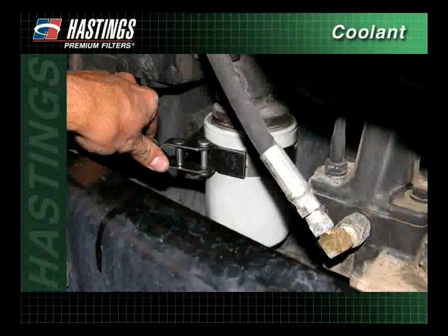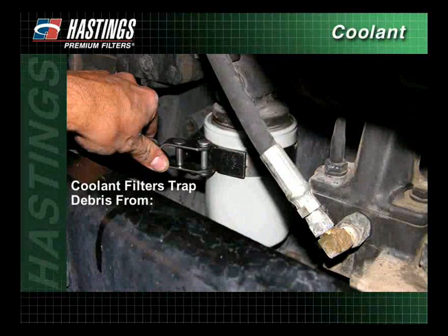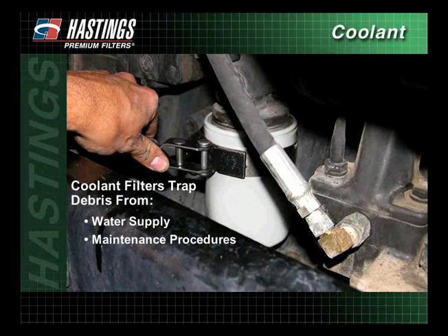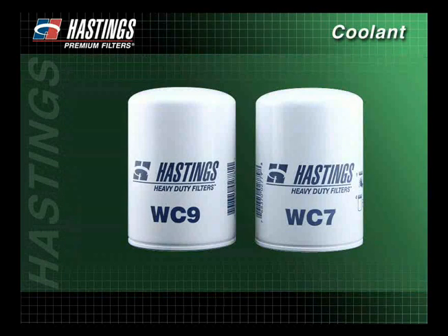Installing a coolant filter is an effective way to help maintain your cooling system. Coolant filters help trap debris from the water supply, maintenance procedures, and combustion byproducts. Choosing the right filter comes down to selecting the best SCA for your system.